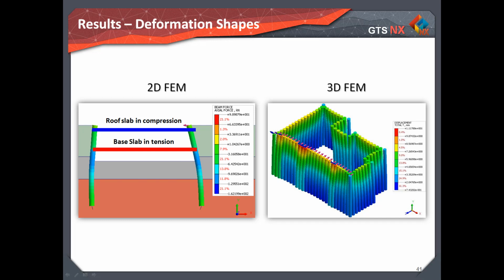And suggested limit equilibrium results look less drastic, though they have not been calculated incorrectly. It is worthy to note that analysis of half section in 2D finite element analysis would not have predicted this asymmetric behavior either. This figure on the right illustrates the displacement shape in 3-dimensional and the location with relatively higher displacement due to moment load applied by the columns. Limit equilibrium method is not capable of modeling this at all.